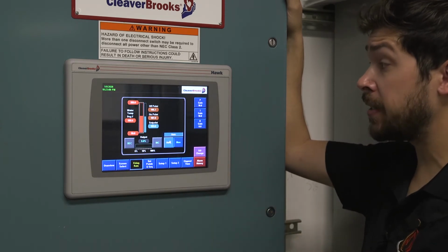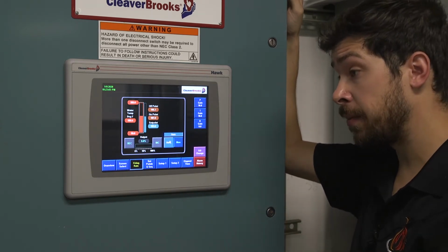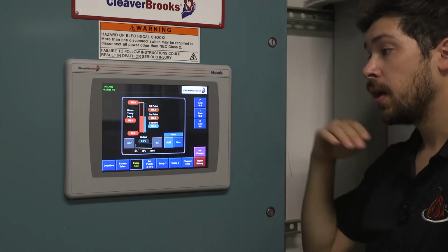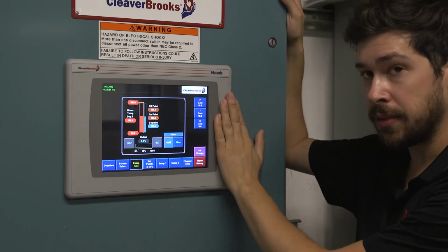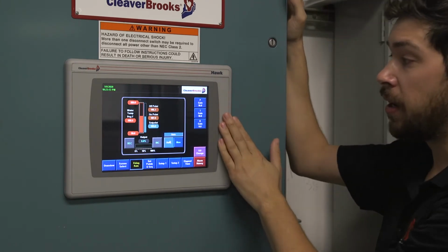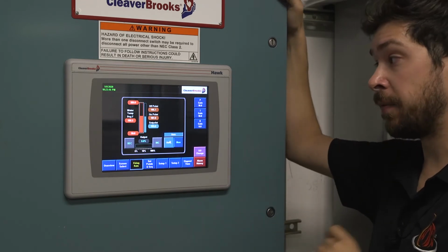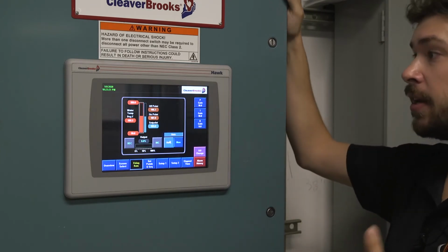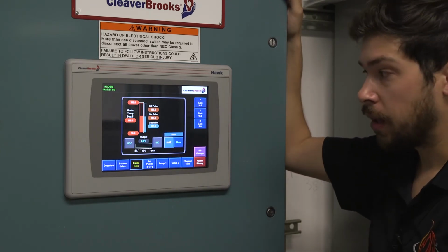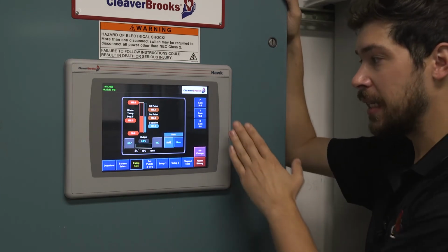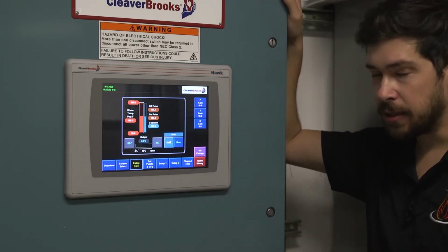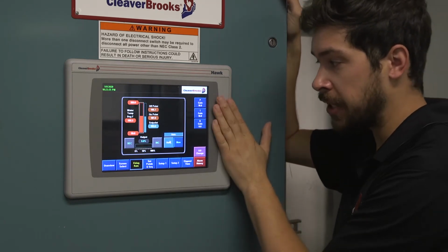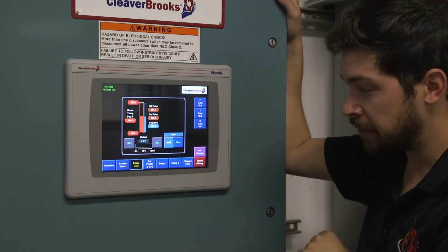These here, the PID gains, if you're familiar with them, great. It's just about how we respond to load fluctuations. I wouldn't mess with these. These are set by the technician when he started it and should be good for the life of the system, unless major system changes have been made, as in you guys built another wing. But even then, 10 on the P, 10 on the I is pretty much all that we ever really use. We never see any on the differential. So I'm just mentioning that they're there and that you should never really have to touch those.